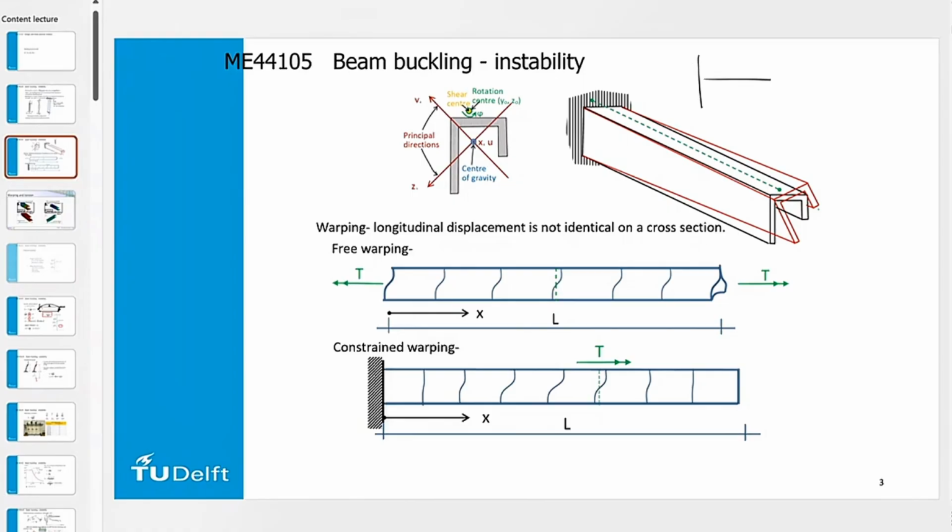If I have, for example, this beam with a load, then it deflects, and then the rotation is considered constant over the height. What does it mean? And the deflection of your beam profile, in reality, that is related to the shear in your beam.